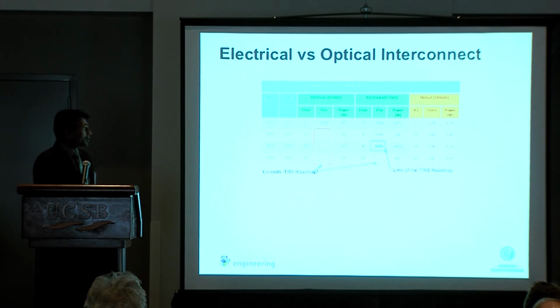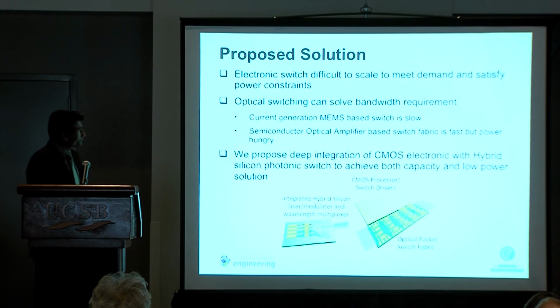And if you need to scale to 400 gigabytes a second, you would need 8,192 pins, which is practically impossible. But in an optical network, by scaling the number of wavelengths and keeping the fibers basically constant, the power consumption doesn't increase very much, and you get the data rate that you want. So this is the right approach for scaling for data centers.